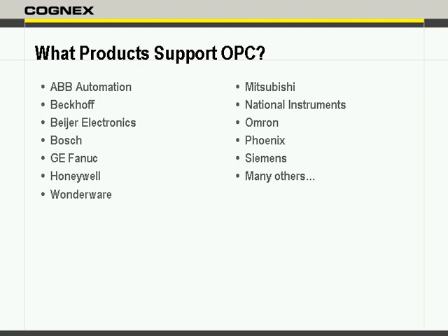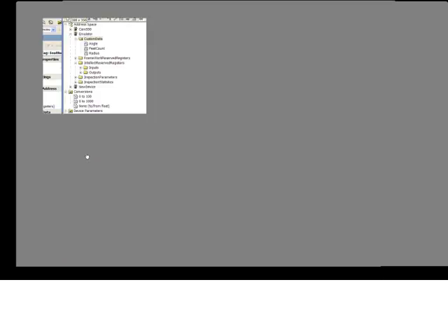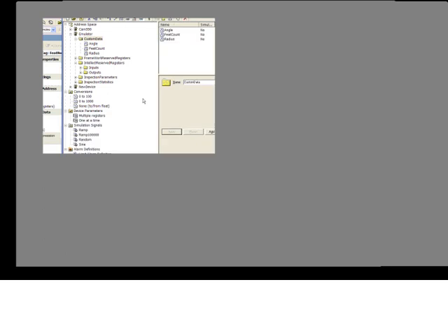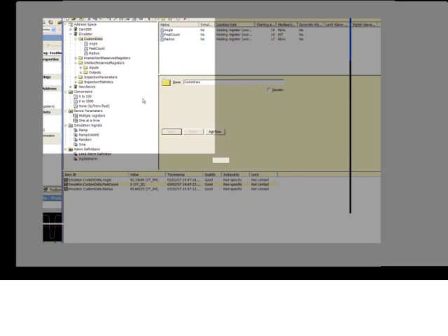Anybody has a specific question? Wondering if you had planned to go over how to get it, what you showed right there was how to get it from the Intellect over to the configurator or the server. Is that accurate? Yes. What would we do if we wanted to get it over to an Excel spreadsheet, for example? An Excel spreadsheet could be an OPC client, and in this case, each OPC client has different ways of configuring connections to OPC servers.